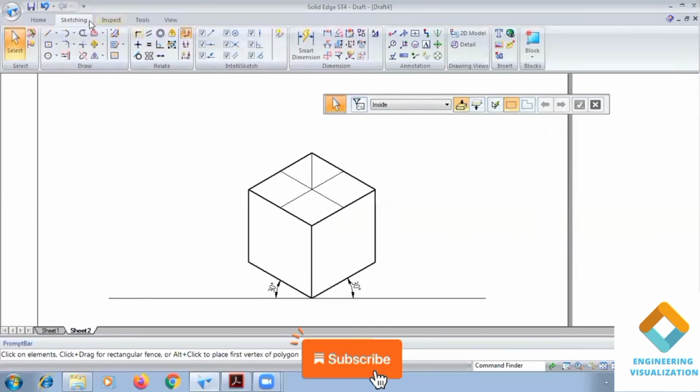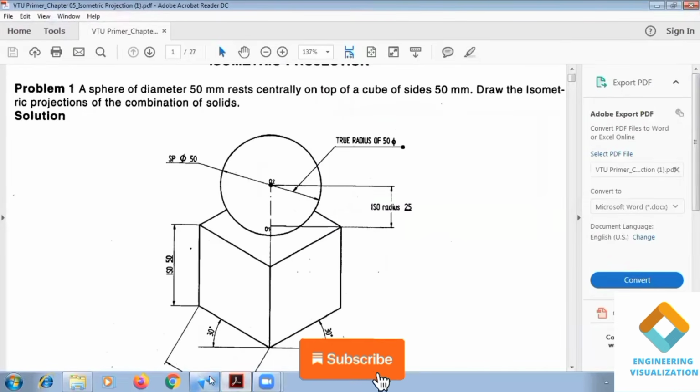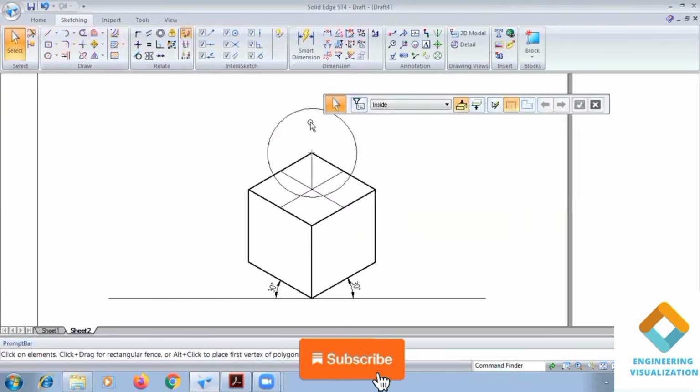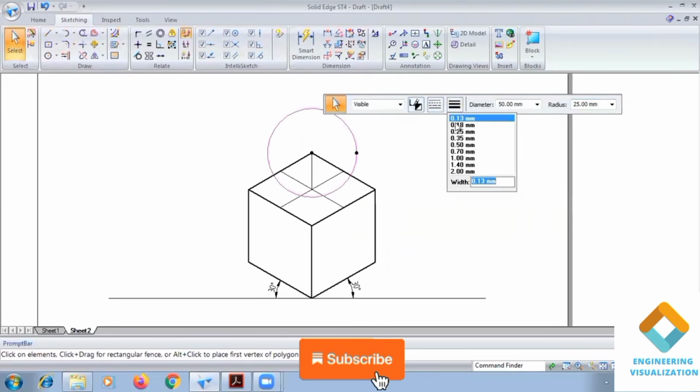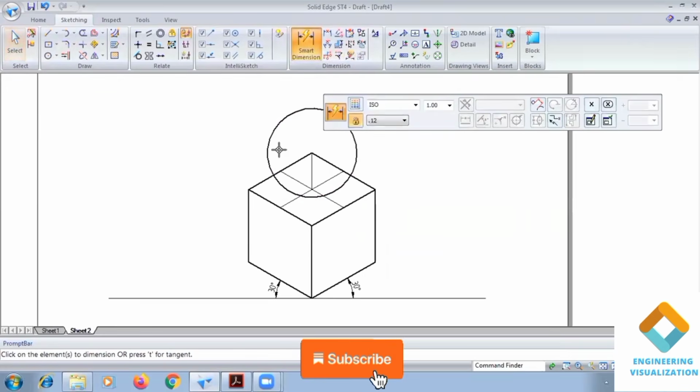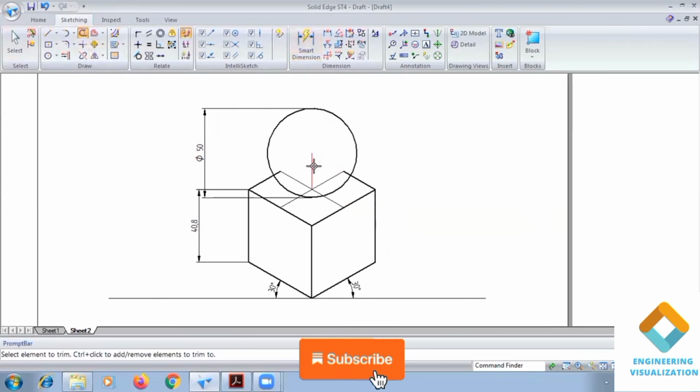Okay, now go to circle and draw here. That's the center of the sphere. Now go to circle and draw a circle of diameter 50. Enter. So that completes the sphere here. So always remember, the sphere will be drawn with the actual scale, other solids will be converted into iso. So you can check the dimensions here. This will be 50, the sphere's actual dimension, but if you check the dimension of the cube it is less than 50, because after converting to iso it is converted into smaller dimensions.